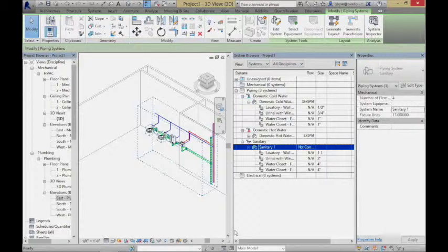Even in a room like this, how much variation can there be? Does it always have to be right at 76 degrees, or can it get up to 78 or 80 and then kick on the air conditioning to bring it back down? It's really about the range of comfortable, allowable temperatures. The more flexibility you give the system, the more energy efficient it tends to be.